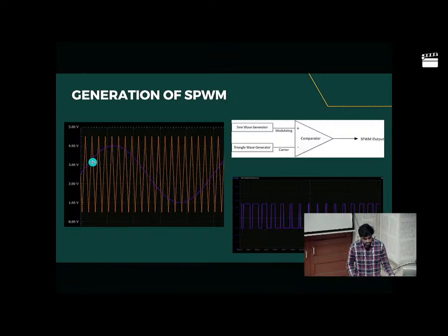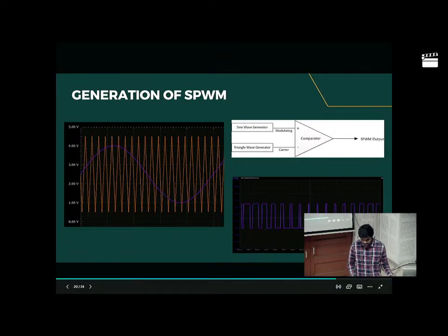The crossing period increases with time as the sinusoidal signal proceeds towards its maxima. So the duty cycle corresponding to the maxima is higher than at the low points. At the low points, as the sine is decreasing, the rate at which the sine signal is greater than your carrier signal decreases, so the pulse gets thinner and thinner.